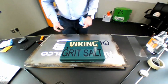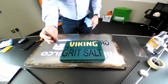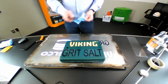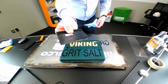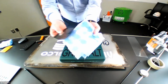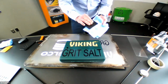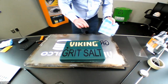And you'll notice the adhesive start to globule. And just using a thin, sharp plastic squeegee again, I'm just going to scrape that adhesive straight off. You just work across like this. I'm trying to show it on the camera here, maybe you can see a bit of goo, and then just depositing it on a throwaway rag like this here. So I'm scraping right over the graphic, and that just really quickly pulls off all the adhesive.